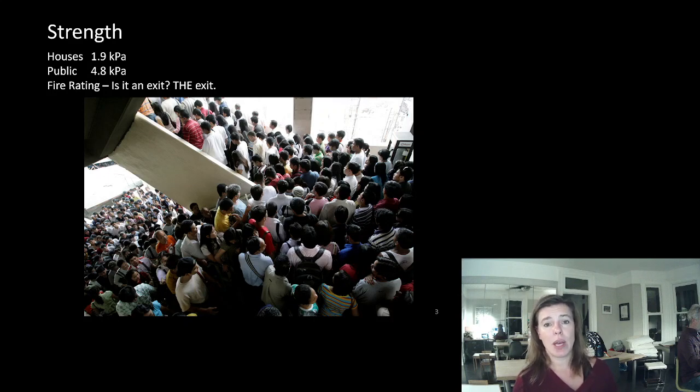If you're talking about a feature stair in a house that's more like a mansion, you're probably going to want to think about 4.8 kPa, because those are the times that they will have a gigantic party, or they'll rent it out for something and there will be video shoots of a party and they will try to make that 4.8 kPa. I know you're thinking, why would you design a stair for a fake video of a stair usage? That was just one I could think of, but I can think of feature stairs in very, very large houses where they would host the sort of party where they could do 4.8 kPa.